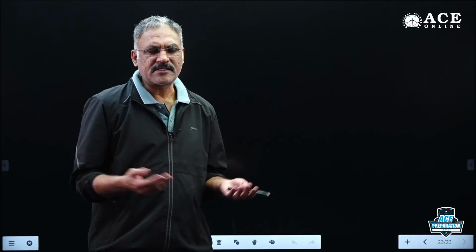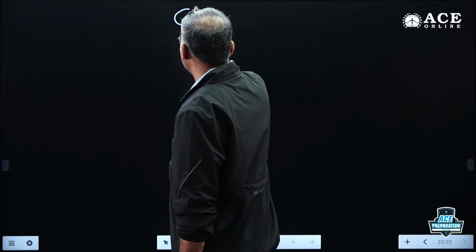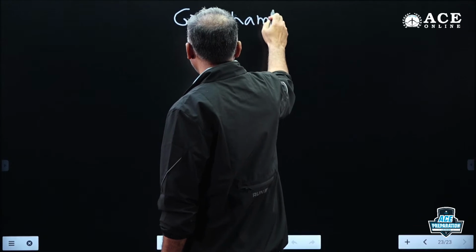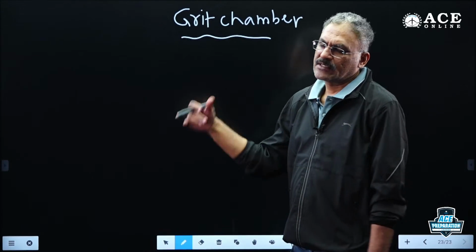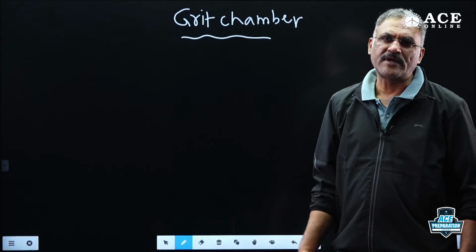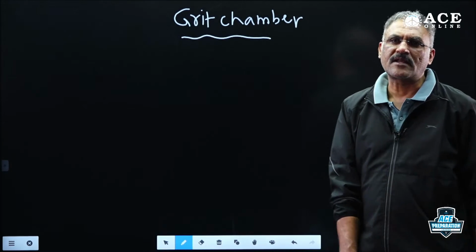That's all. Next, coming to wastewater treatment. We all know that it is divided into preliminary treatment, secondary treatment, sludge treatment, tertiary treatment. So many things are there. In primary treatment, if at all they ask any question, that is only from the grit chamber. Screens and all, not required. The grit chamber design concept is exactly the same as the design of sedimentation tanks. Therefore, more questions they are asking from here.